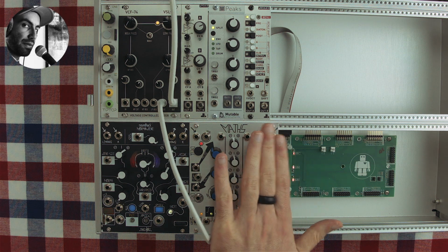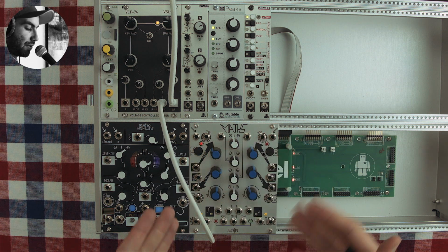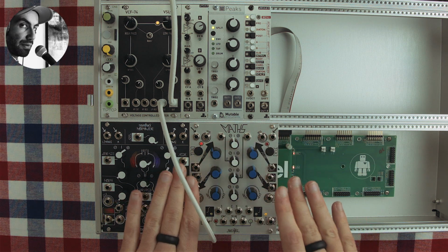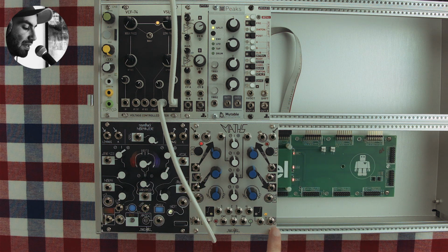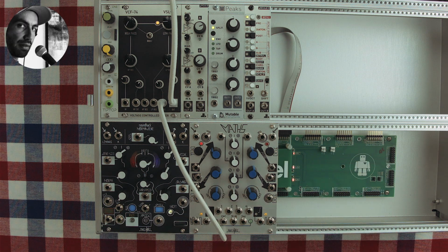All right, so I'm not going to demo the channel 4 here because it's identical to channel 1. So you can just use your imagination and you can see how it can get really complex really fast. The only difference is this end of cycle here, if you remember. So this triggers when it reaches the end of fall instead of rise. And you can use these two gates to sort of interpatch the other two. And you can quickly see how you can get exponentially complicated CV signals.